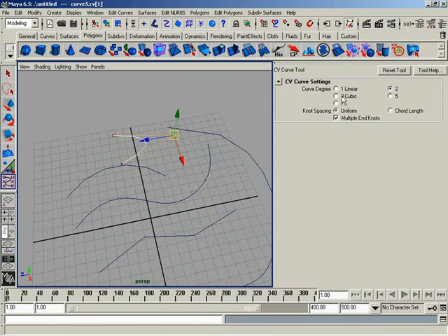When working with a 3-degree cubic, they're also referred to from time to time as S-curves because with one of these, we can cross over 3 times and make an S pattern. And we can simply climb up from there with 7-degree, I think, allowing you to pass like 5 times or something. Now, 5-degree and 7-degree curves are used in design and engineering. CAD people, when developing anything from tennis shoes to watches that are putting things together inside applications like studio tools, will be using very high curve degrees so that they get a very high level of precision. So that's all I want you to know about that.